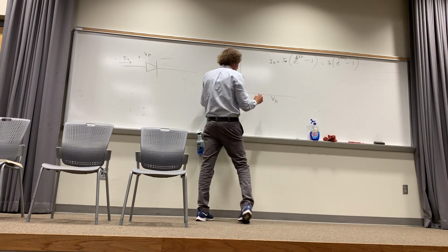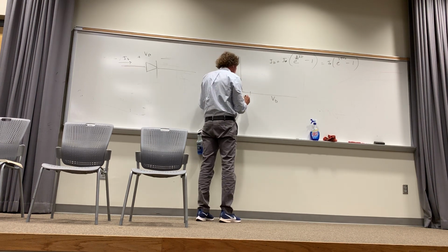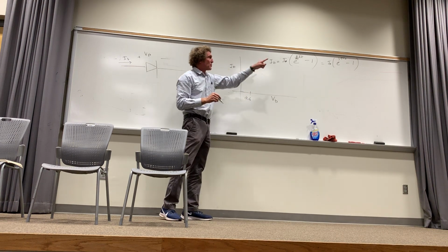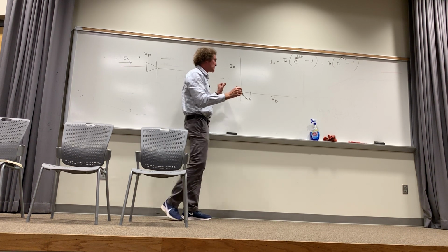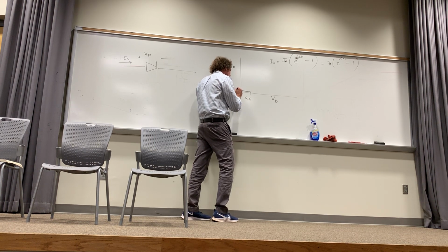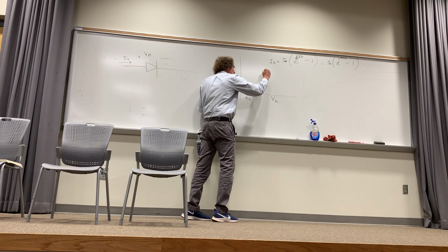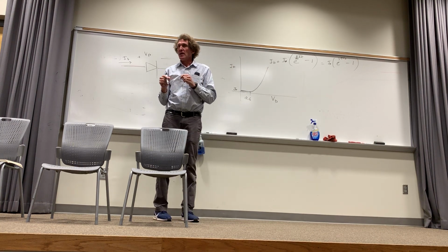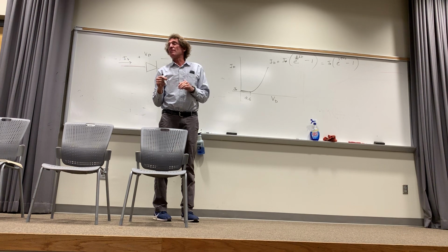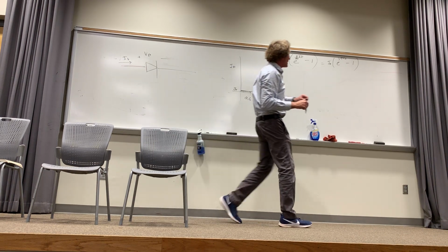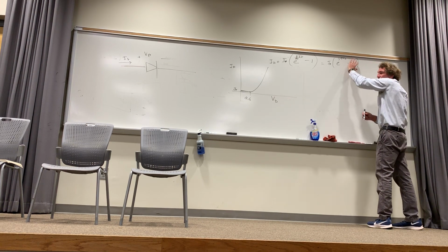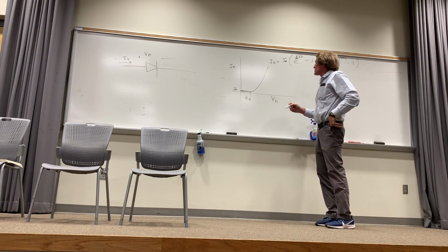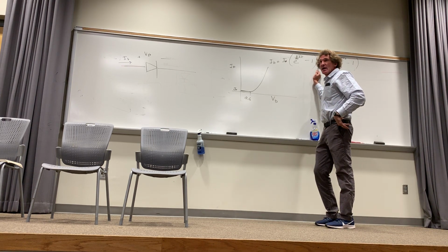If I take a look at this diode curve, nothing happens till I hit about 0.6 volts. You can actually put 0.6 times 39 into there, but it's about that for V diode. And just bear with me on this one, class. Now, at this point, all of a sudden, you're gonna have some very low current here. This will be I naught, and then the current will exponentially start ramping up like this. So the current starts going up faster and faster. You follow me on this, class? It's going up at an exponential rate. We never use this equation for any kind of modeling, unless we absolutely have to.